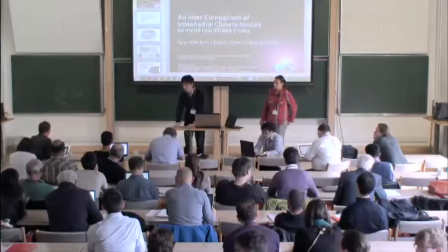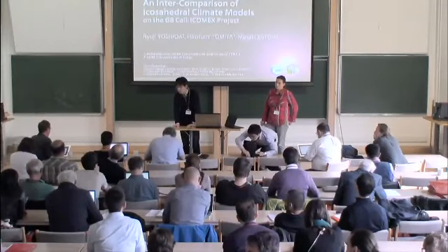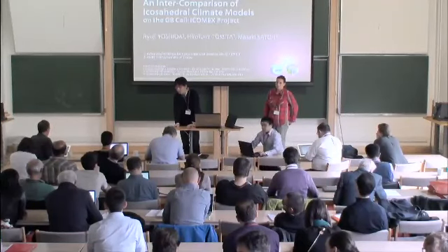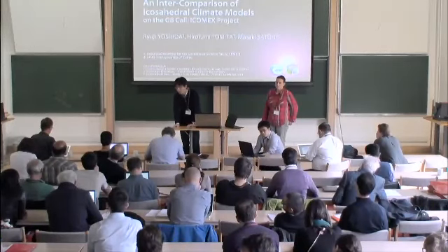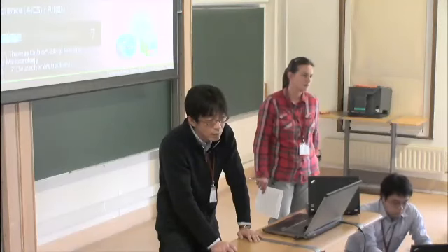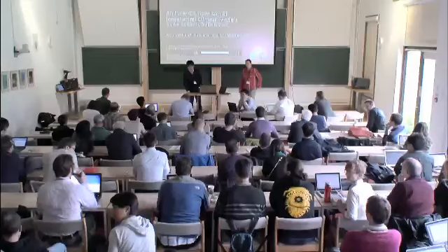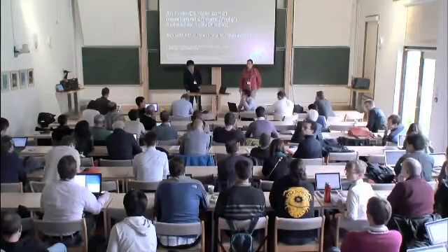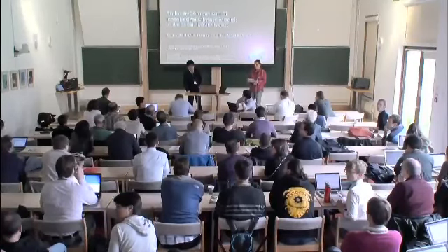But I would argue, at least from my experience of runs in direct numerical simulation and also LES, that you get the qualitatively correct solution with relatively less vertical resolution if you have some form of implicit coupling of the variables. If you go fully explicit, you need much higher resolution to achieve the same result. So to some extent, this issue of the aspect ratio can be alleviated, at least from my experience, by implicit coupling of the dynamic prognostic variables.